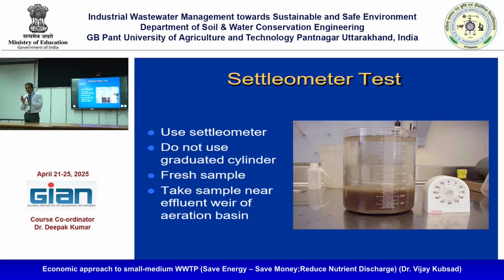When I was working on the particular wastewater coming from the refinery, which has toxicants in addition to BOD, what we did was train the bacteria from the heterogeneous culture to consume cyanide, right? One other contaminant was TC. We tried to train that bacteria, and ultimately we compelled it to remove that. So that is possible. But how is it related here to domestic wastewater?